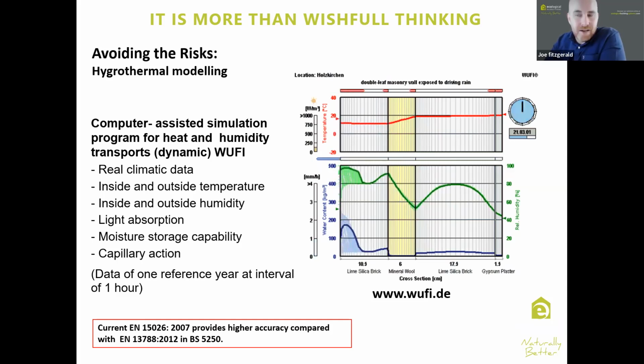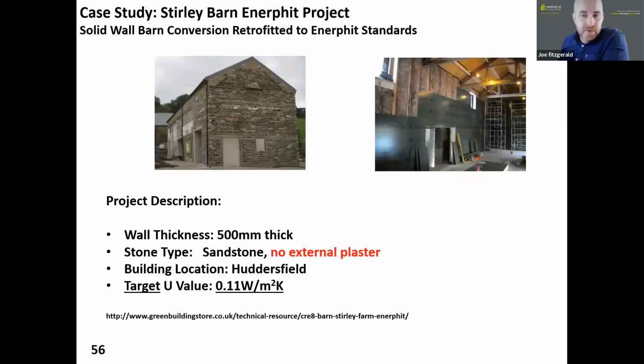And that really is a different type of dew point assessment method than the old EN 13788, which is the standard dew point assessment method. This one will take account of a lot more. The old standard method only looks at vapor moving from inside to outside. So I'd be very careful relying on the old method on anything to do with IWI. It's not very appropriate. We use it all the time, and other companies do too.